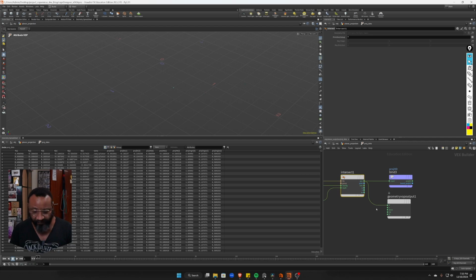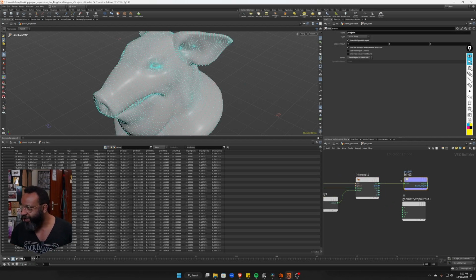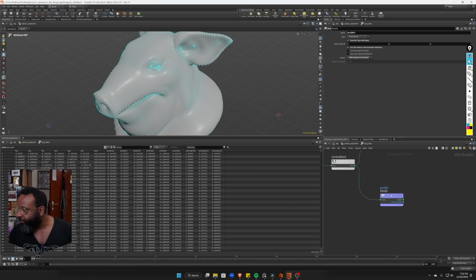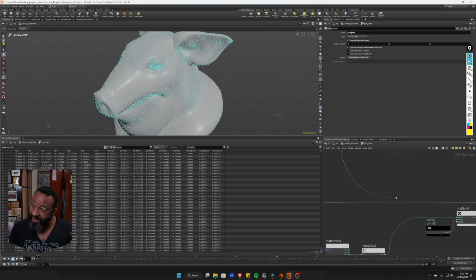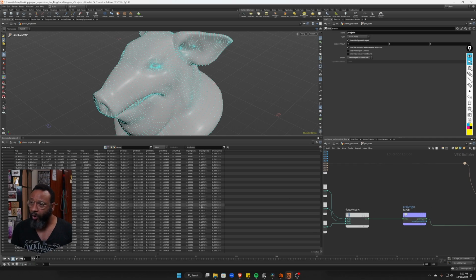All this is being written out to geometry. So this projection hit is being written out to my geometry, which will then be rasterized later. The project direction is being written out. The name's already being written out; I don't really need that, but I have it if I want it. And then there's the project origin. So all this is being pushed down onto our vector-based data, which I will then take into COPS, rasterize, and use as I see fit.